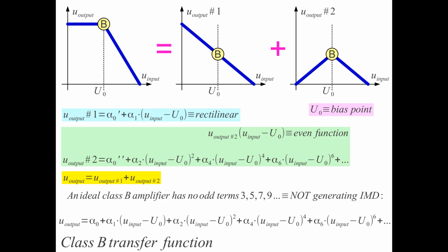We still do not understand where the important point is here. The important point is that we can write this curve with a knee as a sum of two curves. One is a linear response, and the other is a triangular response. So we have these two curves summed together. They give a flat response, so no gain below the bias point, and above the bias point the slopes of both curves add up together, so we get twice the slope, we get considerable gain here.